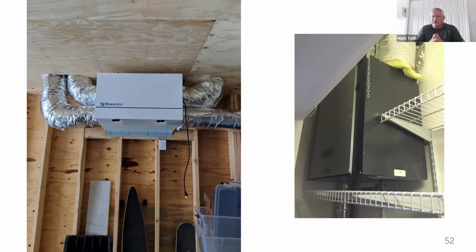So that's the one that we showed earlier that someone put up a sheetrock wall in front of it that we can't open. So how are we going to service that unit? That becomes a big problem. Also looking at the top of that ductwork is not sealed. We just talked about sealing the duct to the unit or to the collar. That flexible duct right there is not sealed to that collar. So if that is the air intake and it's humid in that house, we're going to get icing on that, just like we did in that other picture.